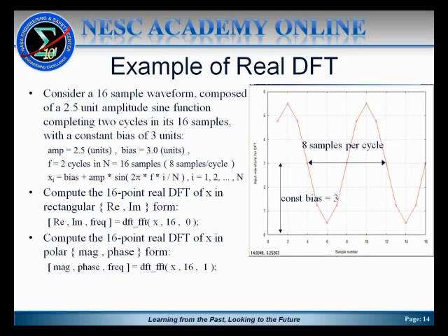basically for illustration purposes, and it uses a fast Fourier transform implementation of a discrete Fourier transform. As I mentioned earlier, if you have sequences of very, very large numbers of samples, it's inefficient to just do what I call the brute force summation, as shown earlier. For a real simple example, it's very easy to compute that summation form directly as shown earlier on the slide.